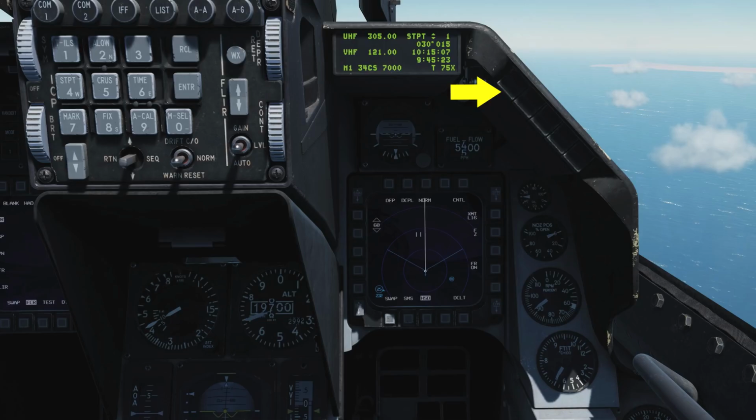The engine fire light will illuminate if fire is detected in the engine bay. Both the hydraulic and oil pressure lights will illuminate if the oil pressure falls below 10 psi for more than 30 seconds, or if either the A or B hydraulic systems is below 1000 psi. The FLCS warning lights illuminate if a malfunction is detected in the FLCS processors, power supplies, input command or sensors, angle of attack, or air data inputs. It will also illuminate if leading edge flaps are locked or the built-in test fails. The DBU light will illuminate if the FLCS digital backup is enabled.